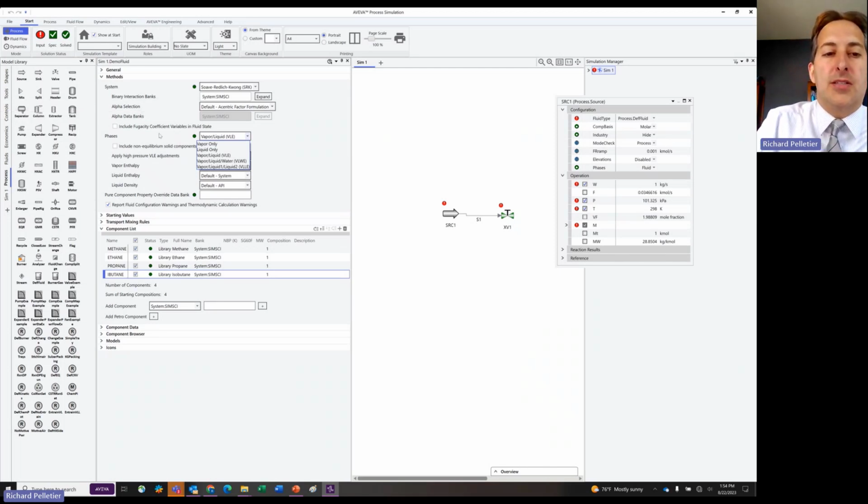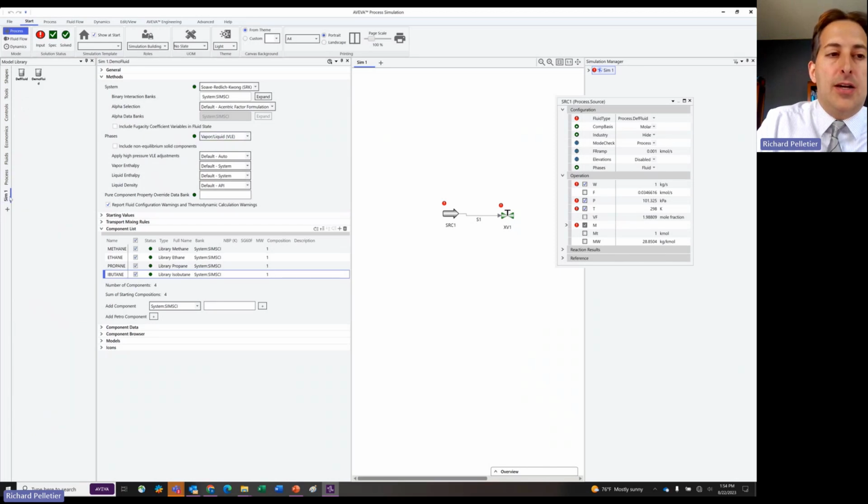All right, so you have to think about these different considerations when you're making these decisions and setting up your fluid. Typically, and I suspect for this example, this competition simulation, you're going to pick your overall thermo method and your VLE probably for your phases, and you're just going to be done at that point. There are no more modifications you're going to do, and no more other considerations that you need to do.